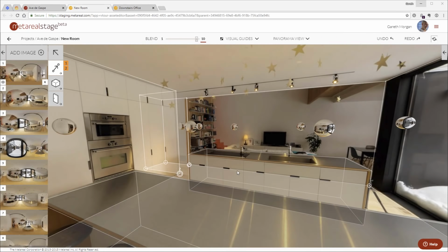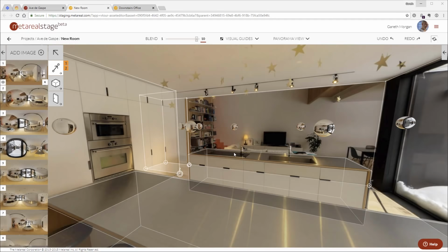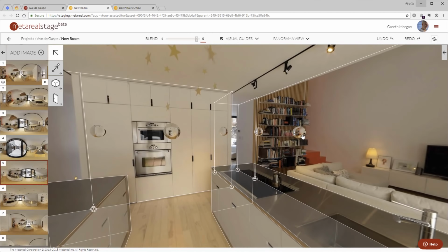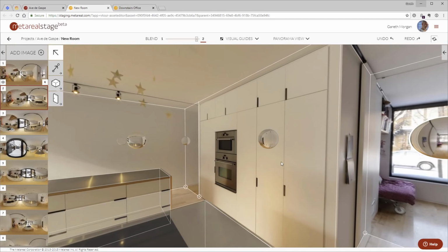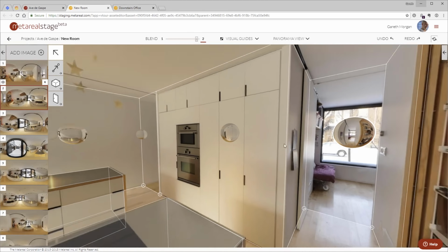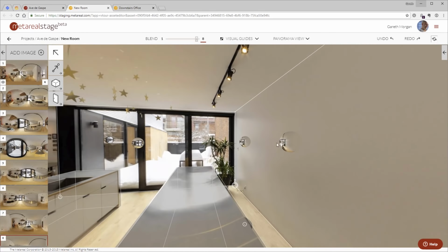Okay, so now we've snapped all those panoramas. The little black lines have disappeared, indicating they're registered, and we've now got, whoops, still in the snap tool, we've now got panorama bubbles showing us all the different panos. And we can also see this one has a white line around it. That means it's the reference panorama. So there we go. It's pretty good.